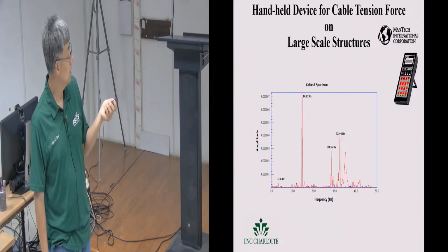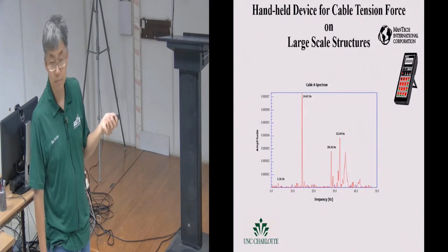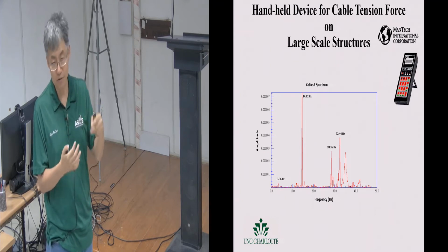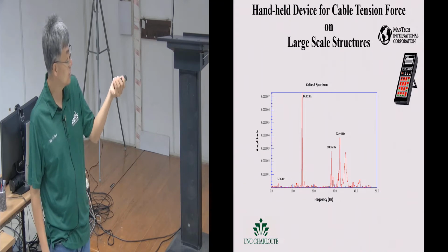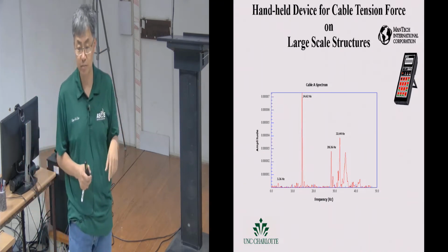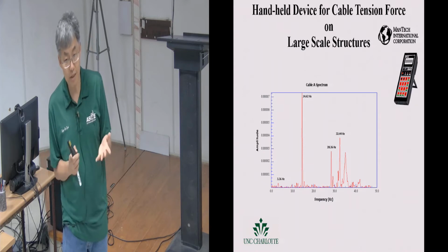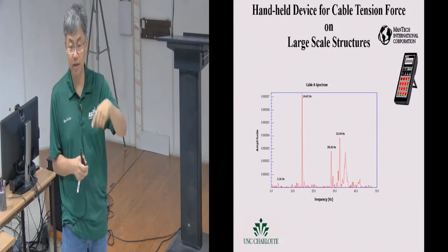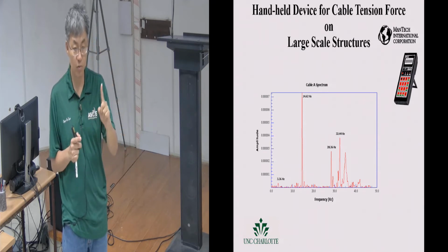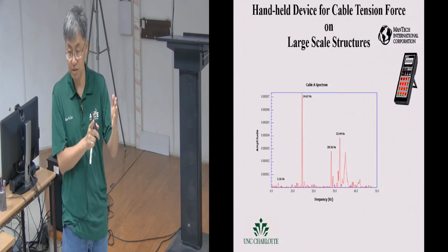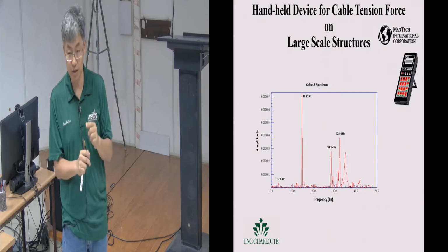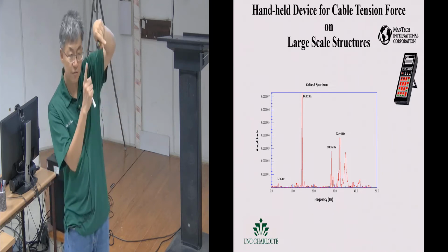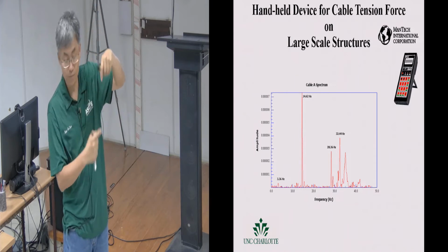And then we also measure the vibrations. Using the device goes into a little bit of the tricky part of the business. You have to develop the algorithm. How many modes do you actually need? Because you're thinking about automating the process, you have to make sure that you always get the same band of frequencies. The goal is to see how the frequencies change. So you need to know, what is this 14.62 hertz? Is that a first mode bending, second mode bending? You need to know, on the string.